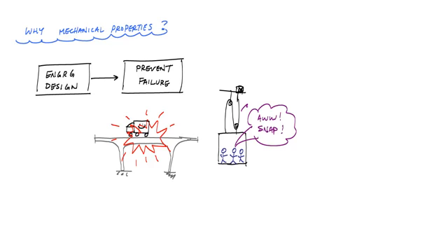Now, we take all of these cases of where something could fail, and we define them mathematically by their stresses, the stresses that occur in the material. And because there are only two types of stresses, most of the time we can just say that what we want in our designs is for the applied normal stress to be less than or equal to sigma allow, and the applied shear stress to be less than tau allow, whatever we allow.